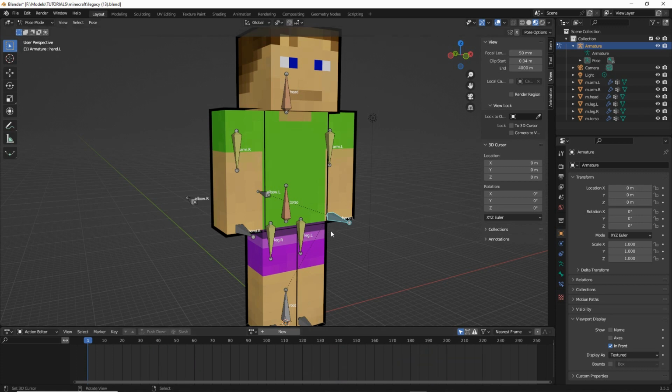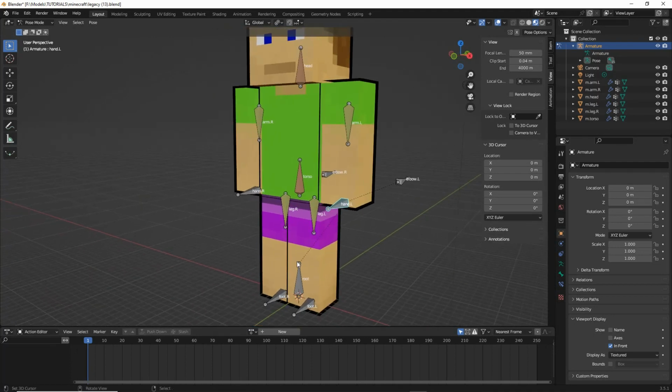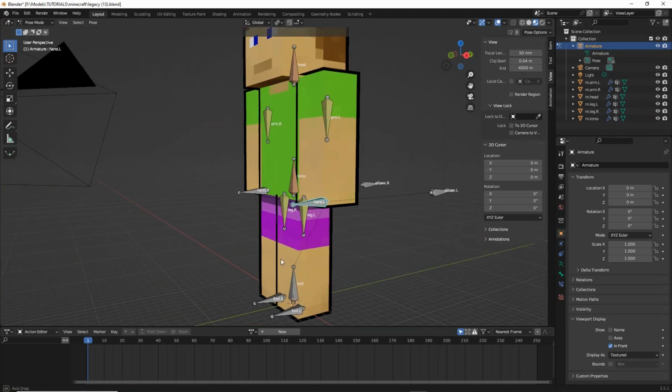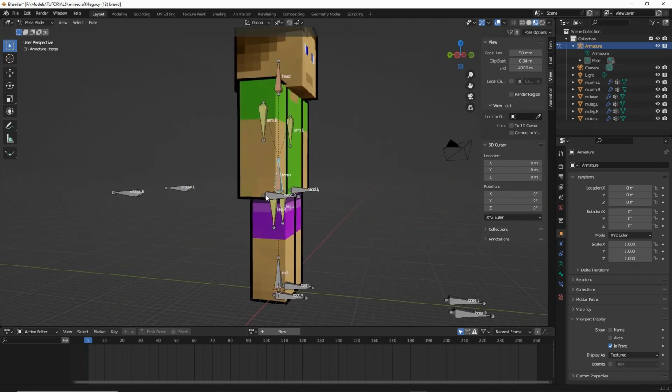And then when we insert keyframes, when we move a bone, a keyframe marker, that's those orange squares that we set previously, one of those will appear relative to the bone that's being posed. So it'll all make sense again when we do it. So let's make a pose where the avatar is picking something up.